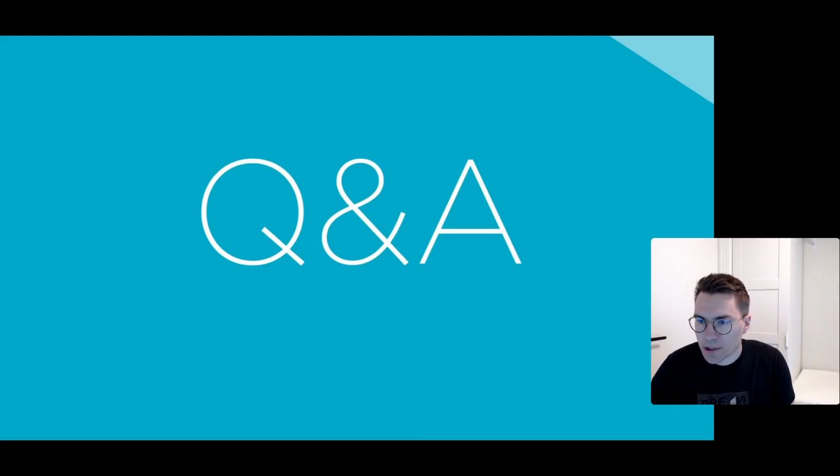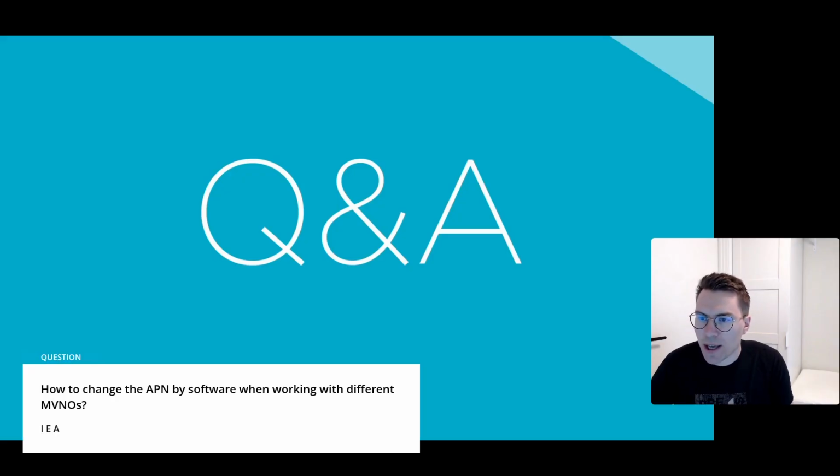And here's another question around how to change the APN by software when working with different MVNOs. So you can either use this AT command. I'll copy it and put it in the chat. And another option is to change this directly in the project configuration file. So you have two options: either send the AT command to the device or put this in the configuration file of your application, and you should be good to go.